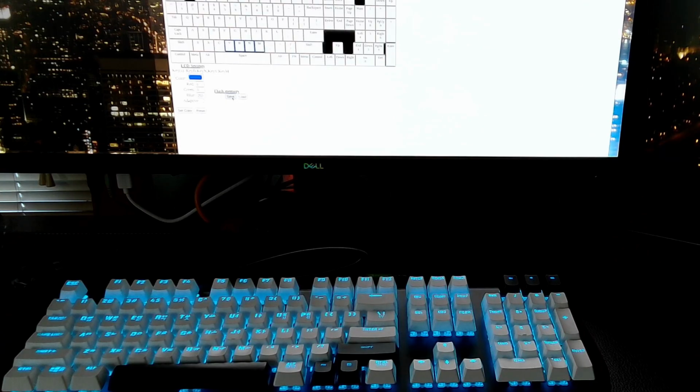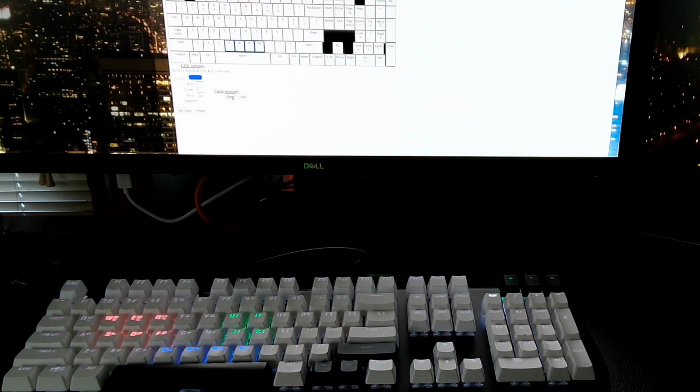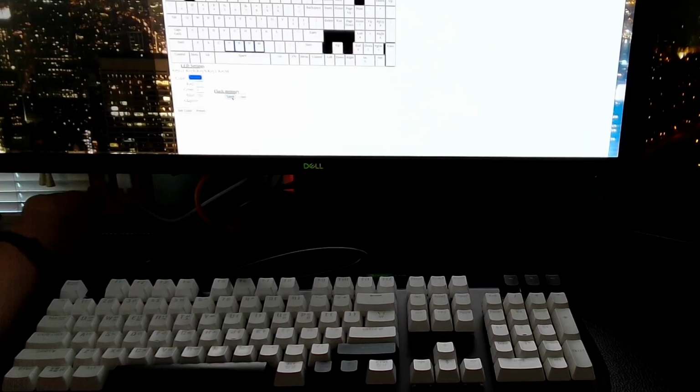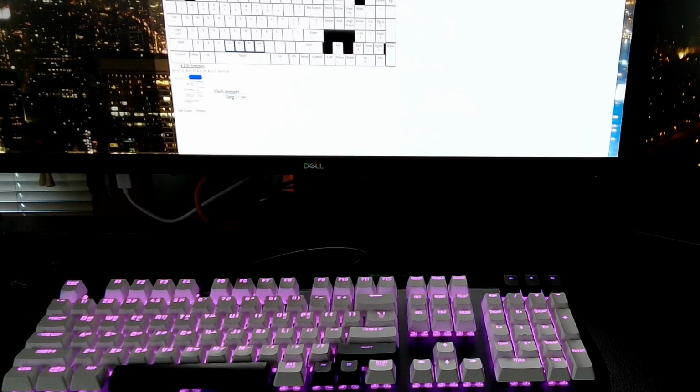And then whenever we power the Pico 2 on, we will first look at that address and see if there's data saved there, and if there is, load it back into memory so that we will be able to preserve those color settings across reboots.